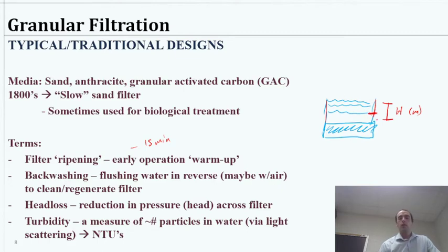And so then the way we operate them actually is we give it a constant flow. And so the water will build up to higher and higher layers and will automatically be pushing harder through the filter. So it's actually a pretty convenient way to, we know we can produce the same constant amount over time, and it'll just keep increasing until it's reached some sort of a limit.